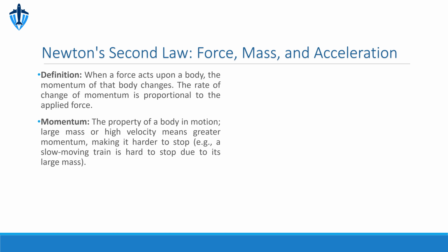Every lever has 3 key parts: the fulcrum, which is the pivot point, the effort, which is the force you apply, and the resistance, which is the weight or force you're trying to move. The distances between the fulcrum and the effort and the fulcrum and the resistance are known as lever arms. The figure illustrates these components in a first-class lever.